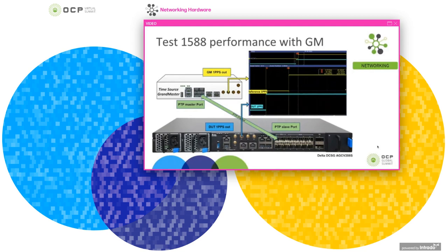time synchronization. But how do we measure it? You can see another yellow and blue line here. That is the 1 pps output. It is hard to measure the central timing of the machine from the packet, so we use 1 pps to measure it, because 1 pps indicates the nanosecond rollover point for each system.